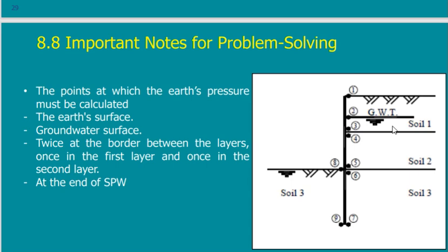Because I have two problems. As we said, if we have water, we need to study the effective stress. But we said that water also has horizontal pressure, and this will affect the wall. So you can tell me that I can ignore the effect of water and use the total stress, but it's not always the case.